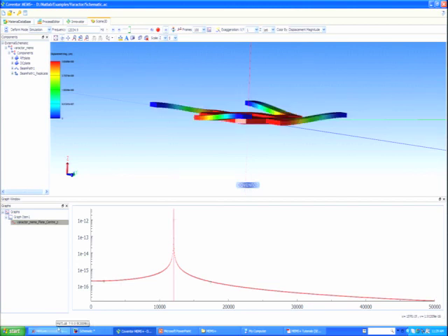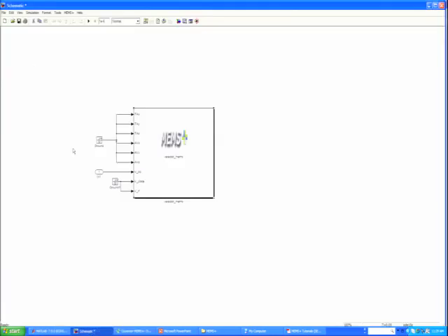The second thing we're going to do, it's just as fast, is a DC analysis. A DC operating point is a static result, it's a static analysis. We put 0 volts on it or 10 volts on it and see what the initial displaced condition is. What I'm going to do is sweep the voltage from 0 to 10 or 0 to 15 or whatever and see at every one of these voltage points what happens to this device.